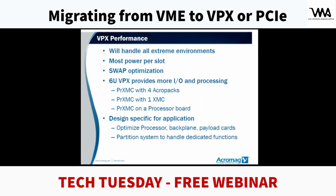VPX performance. One of the great things about the performance of VPX is that it'll handle all extreme environments. And another key factor is it offers the most power per slot. In some instances, you can dissipate over 300 watts per slot. But how to cool that becomes a key difficulty in figuring that out, whether you go with liquid cooling and other types of cooling measures. Size, weight, and power optimization. VPX has been extremely good for SWaP optimization.